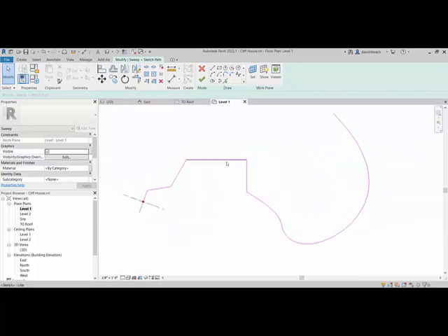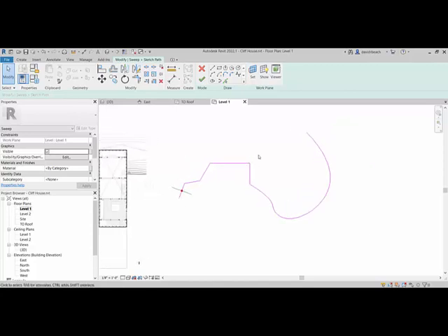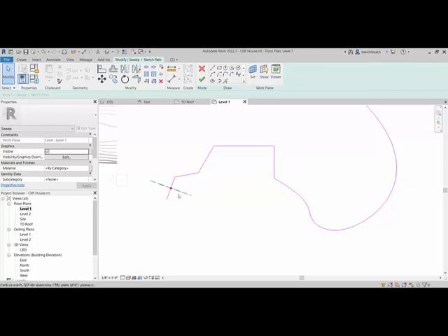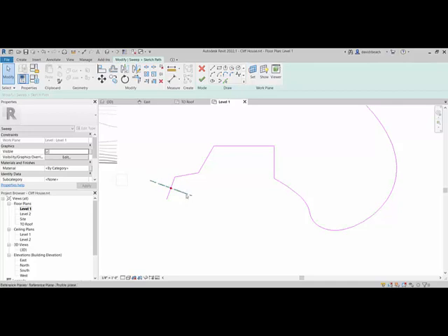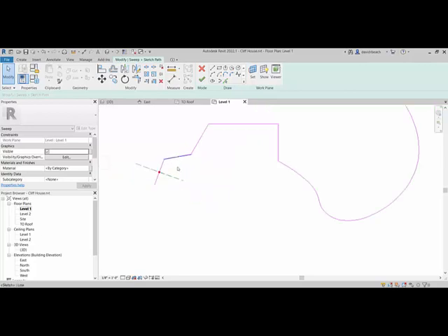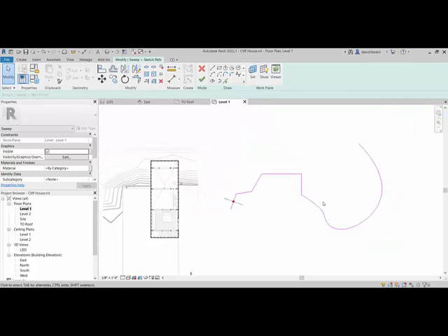It's important that the path, you kind of can, but you really shouldn't, cross back into itself, right? Because if you think about trying to build a piece of geometry where it's intersecting itself, Revit's going to say, no, the real world can't do that, right? Sometimes it'll build it for you. Often it's not going to. That's really often an error message that I see in terms of building these. This is my reference plane for the path, this little dashed green line right here. So whatever I put on this reference plane as a closed loop is going to project along that path.